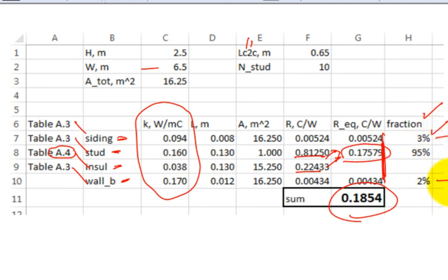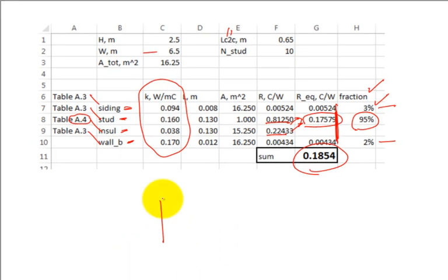And then wallboard on the inside. Again, that's not for resisting heat transfer. It's a whopping 2%. When you have that stud insulation combination, where most of the wall is insulation between structural supports of studs, there you go, 95%. Somebody says, if you want to build a super insulated house, sure, put a 2x6, you get more insulation, right? That's why they put a 2x6.